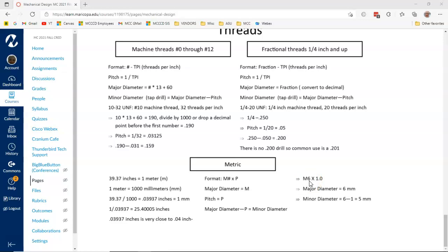And the actual, if we look back at our chart, is going to be about 2.36 or 0.236. And then an M5 times 4 is 20, so multiply by 10 gives me 200. The actual is 197. So I can be within 5 thousandths just by quickly using that information to understand the translation.